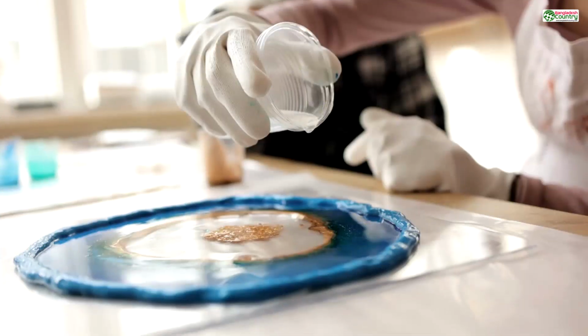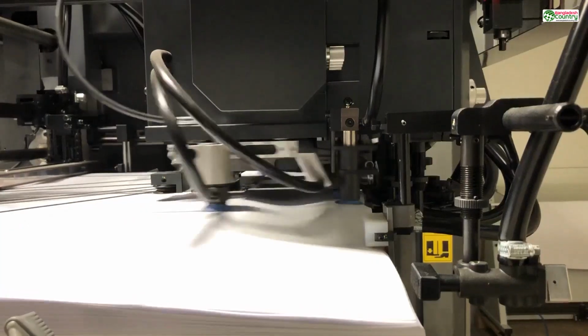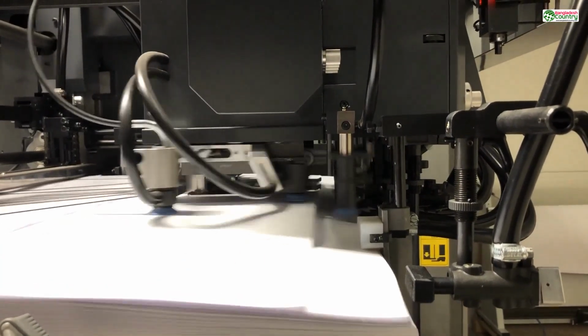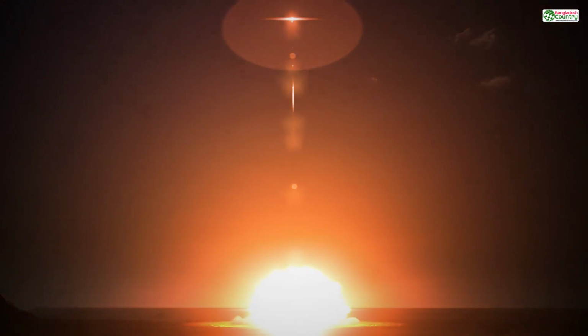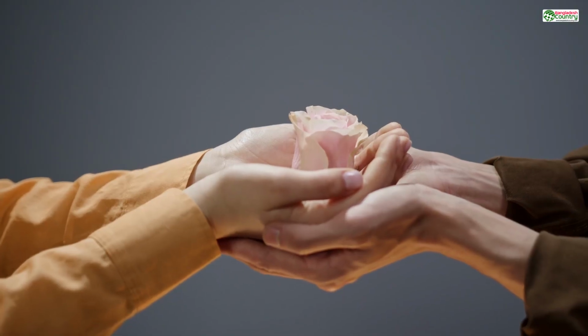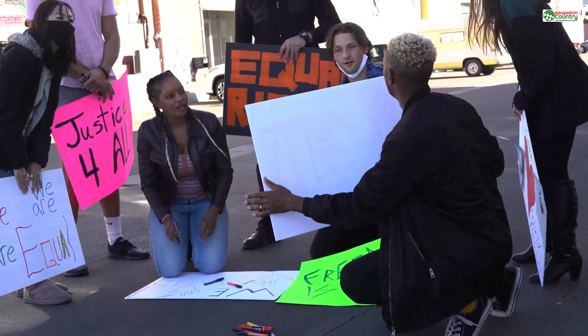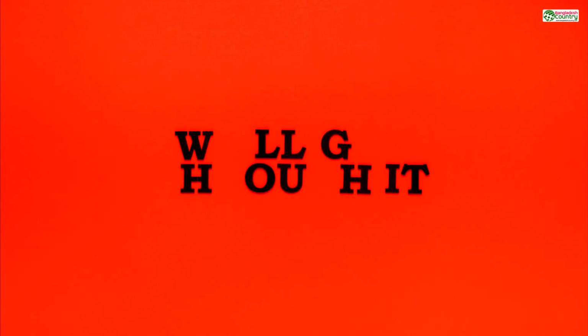While a resin printer might be able to form a paper-thin wall, that wall is now suspended in a vat of liquid. After the print is done, it has to be washed in alcohol, blasted with compressed air, and cured under a powerful UV lamp. Your delicate, wafer-thin wall, which looks so good on screen, will fold, warp, or snap clean off during this violent post-processing stage. It's like a beautiful butterfly wing trying to survive a car wash.